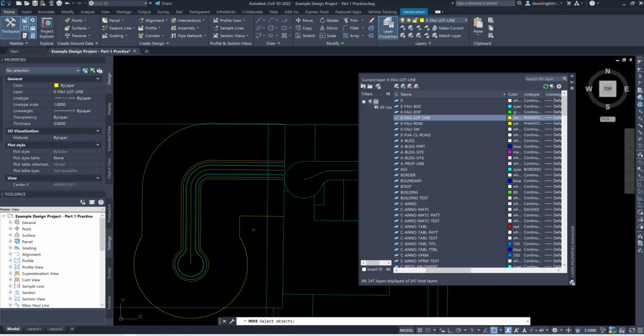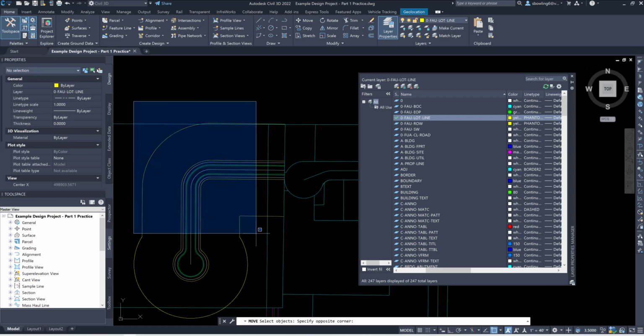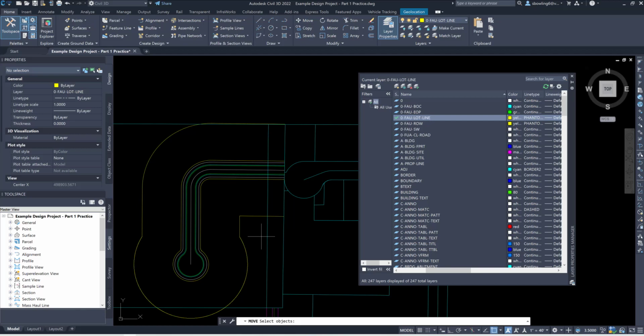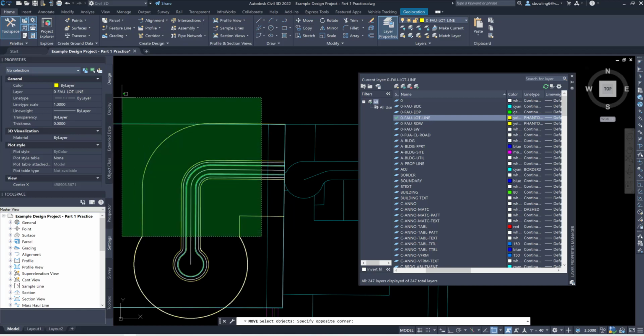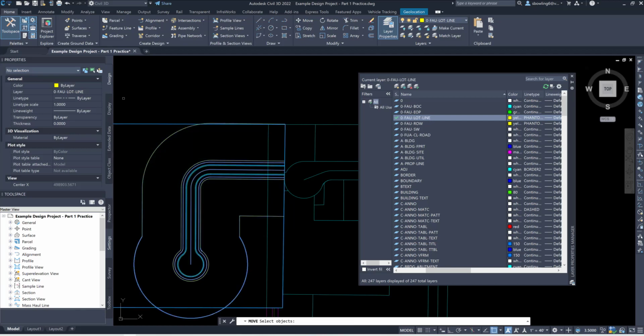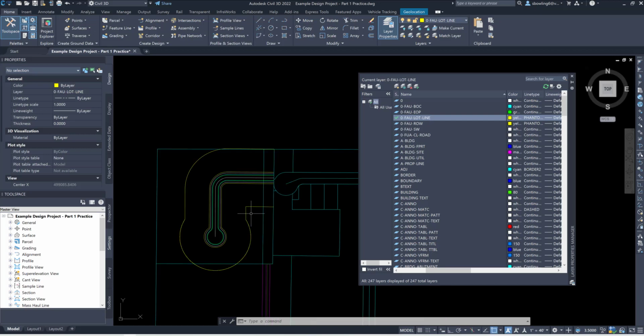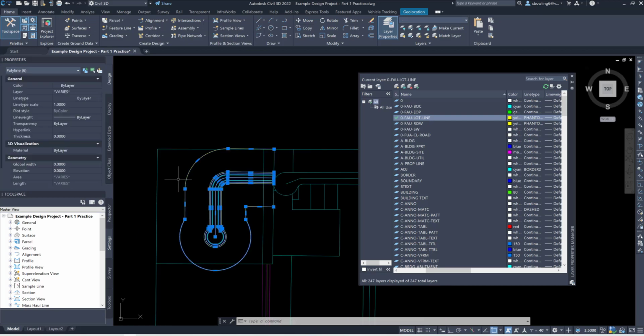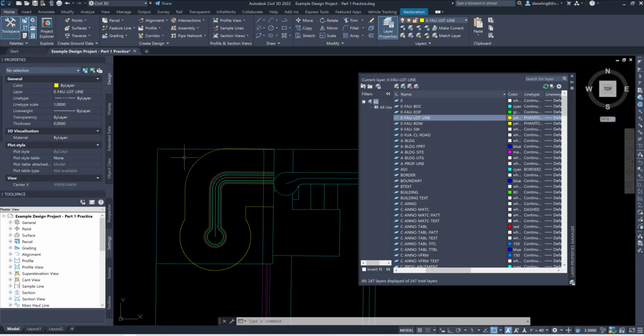If you select an object, there's two different types of windows. You can pick from left to right, see how it's blue, or you can go right to left and see how it's green. If you go right to left, it's only going to pick the objects that it's encompassing. Okay, so I am going to pick all of these objects, because if I do it this direction, notice it didn't pick anything.